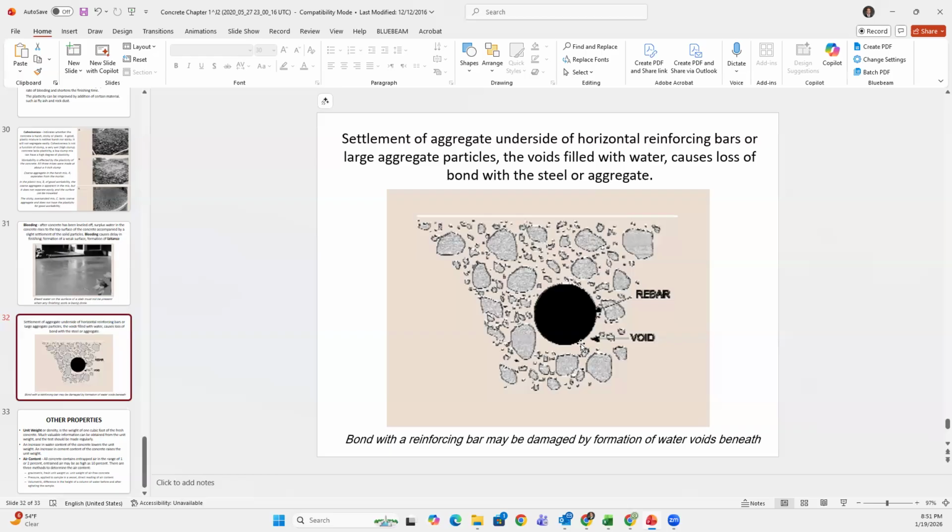So one thing they ask you to ask the contractors to do when they pour concrete is to use a vibrator. They vibrate to make sure that these nooks and holes, these areas, don't become voids. The key to good reinforced concrete is the adherence of the concrete to all sides of the rebar.